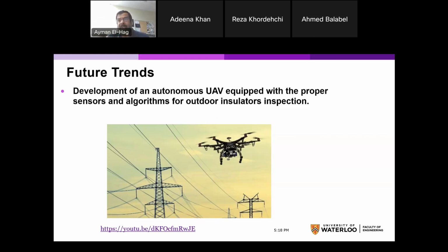And now the new trend is trying to do the classification on board, meaning that you have a microcontroller, you receive the signal, you run the machine learning algorithm, and you come up with a decision. Oh, this insulator is polluted. Oh, this insulator has a crack, has a physical damage. Oh, there is some corona here. Okay. And then you communicate that to the engineer.